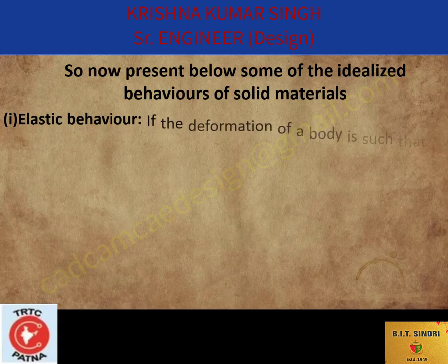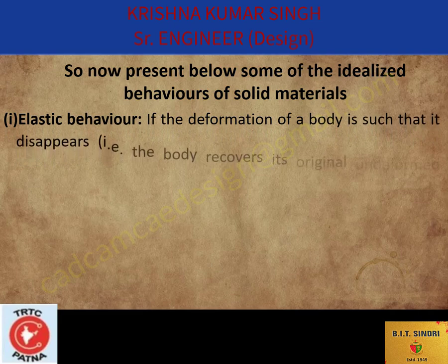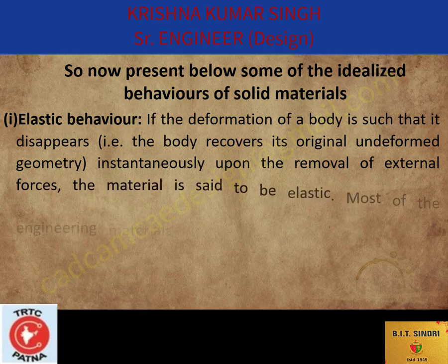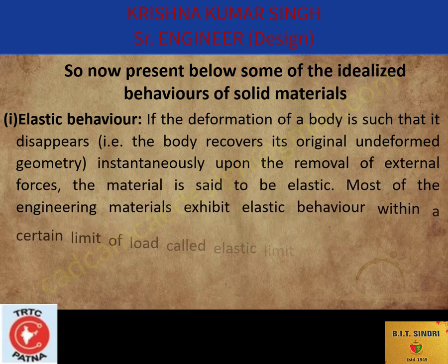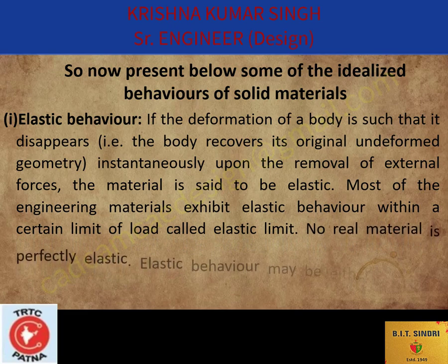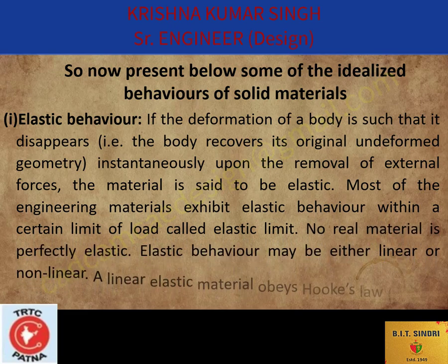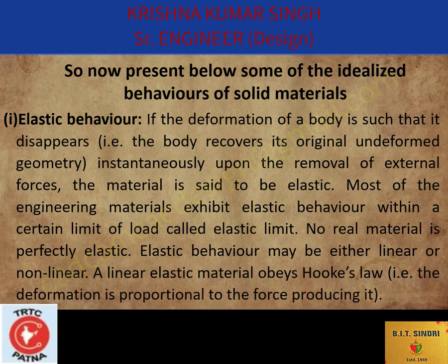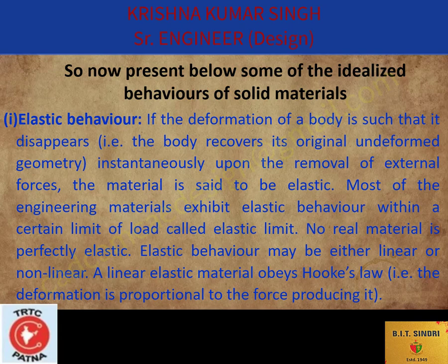Point number 1 is elastic behavior. If the deformation of a body is such that it disappears, that is, the body recovers its original undeformed geometry instantaneously upon the removal of external forces, the material is said to be elastic. Most engineering materials exhibit elastic behavior within a certain limit of load called the elastic limit. No real material is perfectly elastic. Elastic behavior may be either linear or non-linear. A linear elastic material obeys Hooke's law, that is, the deformation is proportional to the force producing it.